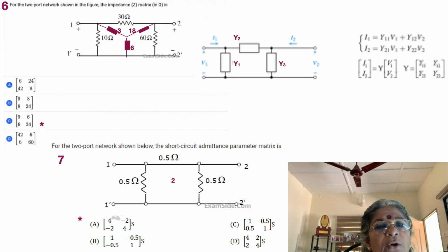So 2 happens to be common as the admittance value of all the resistances. Now we have 2 plus 2, 4, and 2 plus 2, 4, for y11 as also y22. And then minus 2 will be the quantity which is common with respect to y12 as also y21. It's very simple, but certain conventions need to be thoroughly understood and remembered.